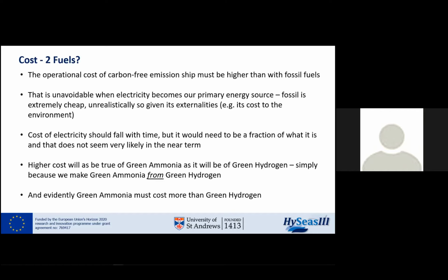One of the things we realized when considering fueling the vessel, and this is closely related to this type of model we're doing, is it's very difficult to store very large quantities of hydrogen as a gas. We could switch over to liquid hydrogen, and indeed some people are looking at that, but as soon as you do that, you're looking at 14, 15, perhaps more % energy involved in liquefying that hydrogen.